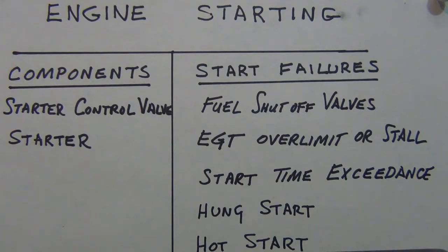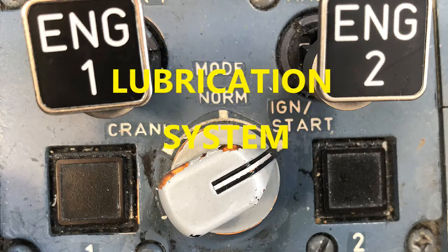With manual operation, a caution here: you don't want to operate the valve manually when the valve is not pressurized. So just keep that in mind. The valve needs to be pressurized if you're going to be manipulating it. Otherwise, you're going to damage the valve. Okay, and lubrication is important for anything that moves, in mechanics. There's a lubrication system that's a wet splash type that's operating under high temperatures.